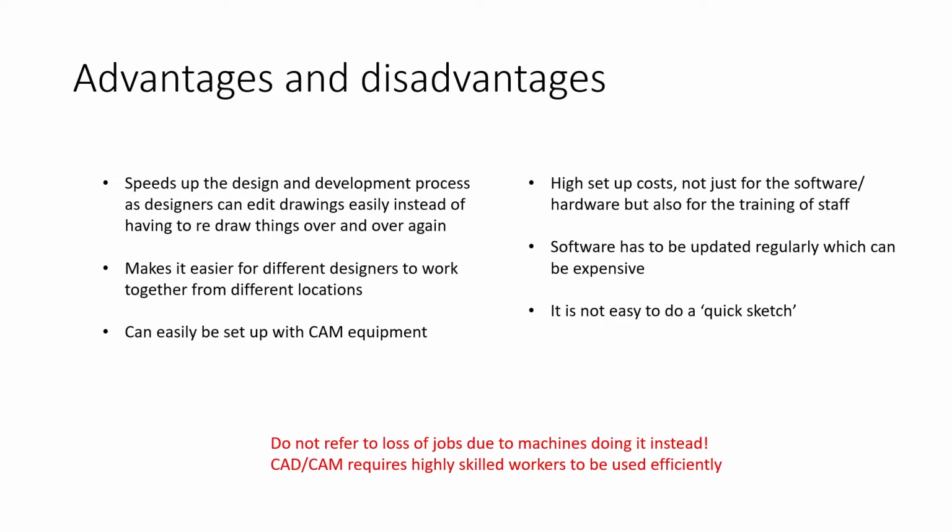If you take Fusion, for example, because we use Fusion 360 a lot in college, once you're doing a design, it's very easy to make developments and make changes. Once you've got your base model done, you can always go in and remodel. You can change materials really easily. You can make tweaks to it. You can add fillets to it. You can change dimensions of it. Particularly, it's parametric modeling, which means you can change dimensions and the whole thing will change with it quite easily. So before then, you would have to just redraw it over and over again.